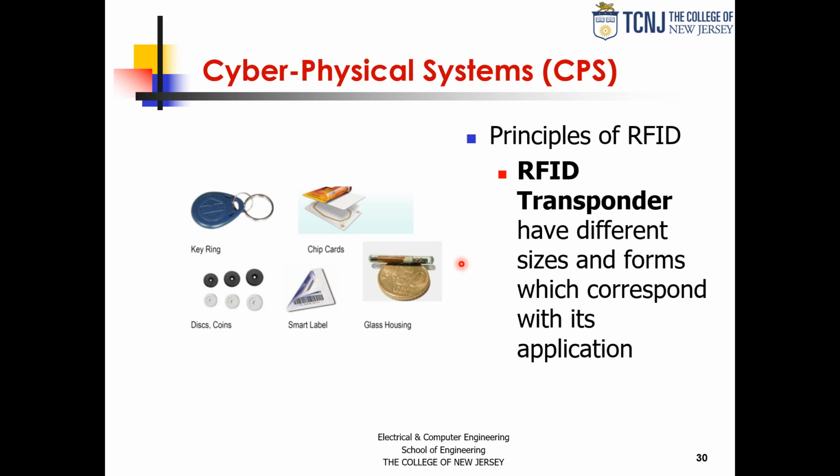One part of the design of the system is to understand very well the size and the range of your application, so the antenna design is important. Because you don't want to overshoot the range either. If you have multiple readers and you want to associate some tags in the vicinity of a reader, and you overshoot your range, then maybe the other reader gets confused. So that's a system level concern that you need to take into account depending on your application.